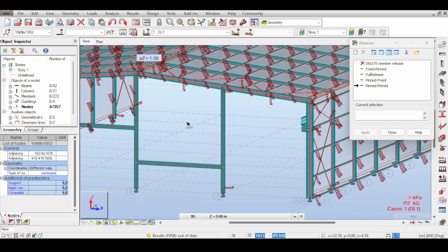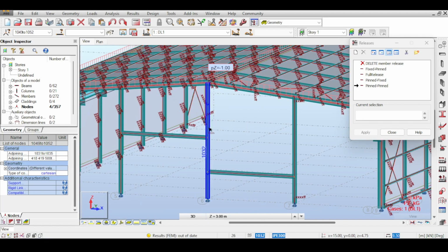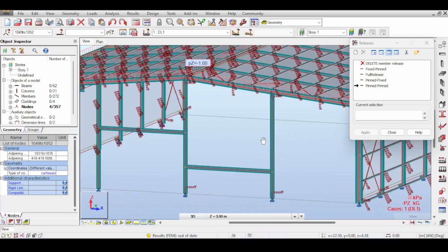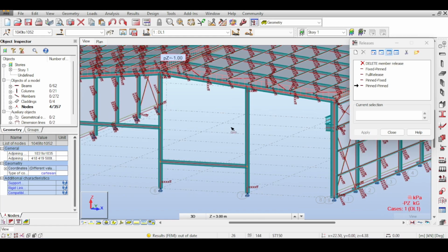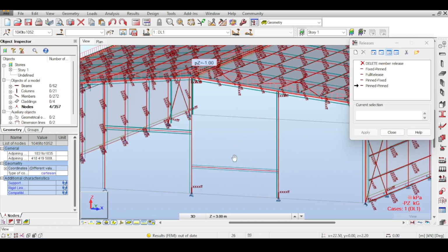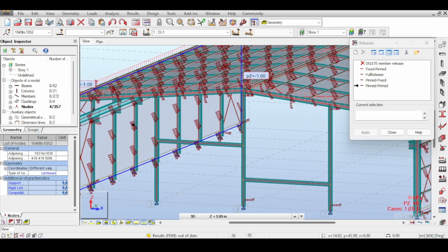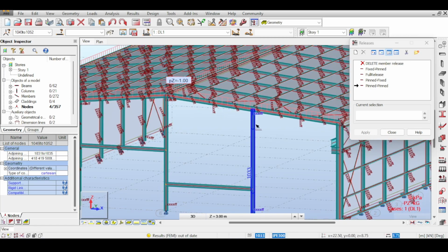If it wants to rotate, I am not afraid of rotating in the XZ plane or in the YZ plane, but I'm afraid of rotating around its own axis. But having a frame action here will prohibit it rotating around its own axis. So my gut feeling says yes if I double pin it.